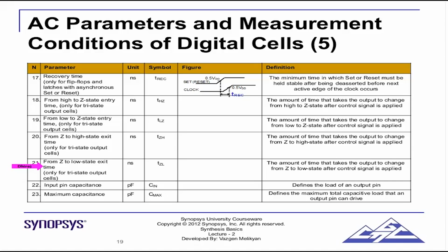Now apart from the timing constraint, the propagation delay, we also have something called the inherent circuit design parameters. For example, there is input pin capacitance. It is the load, and the type of it should be defined through the input pin. The input pin capacitance represents, for example, for an AND gate, or let's say an inverter, you are driving an inverter. What is the capacitance of that inverter's input pin? As you know, in CMOS circuits, the input is usually connected to the gate. Now that gate has some capacitance, so this is the capacitance we are talking about.